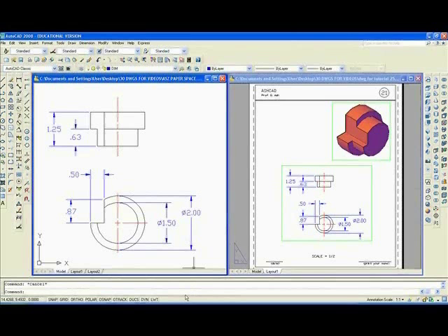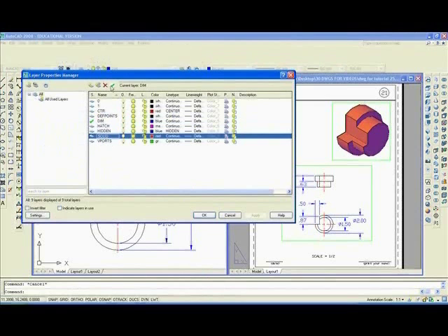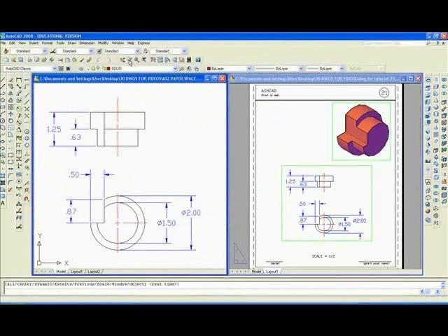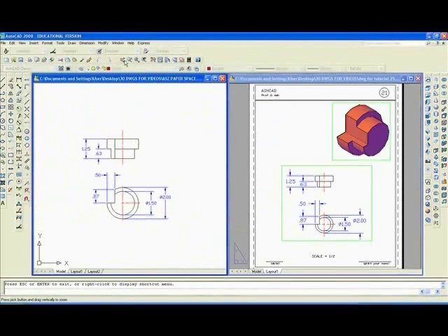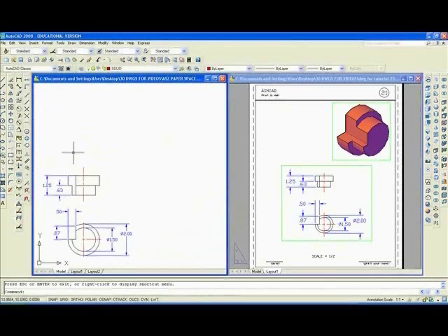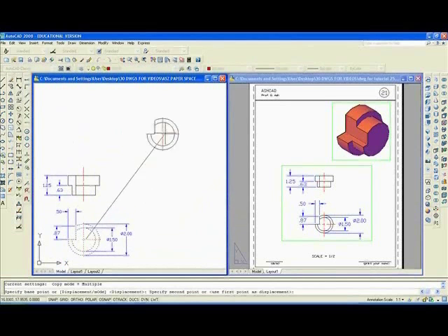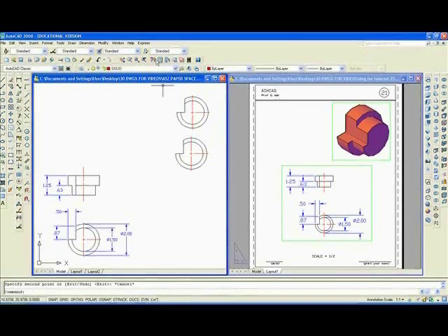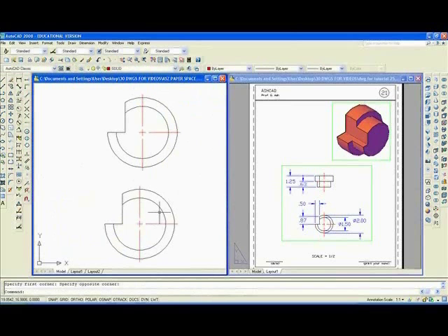And now I guess we're ready to make the solid model. So we'll go to Layer and make Solid Current. We'll use Zoom Real Time to shrink this down, and then Pan to put it in the lower left. Then I believe I'll copy the front view and make 2 copies like that. I'll zoom in on the copies,